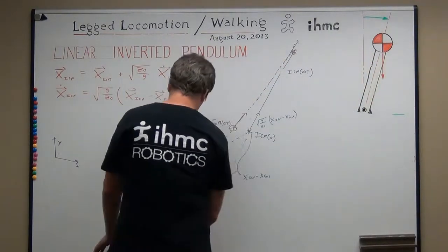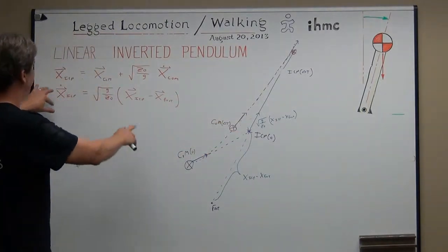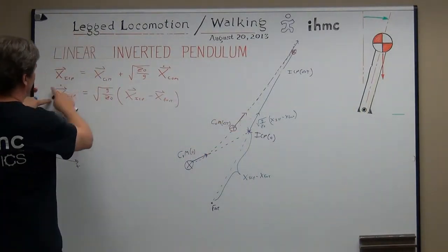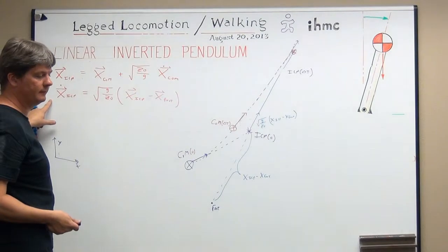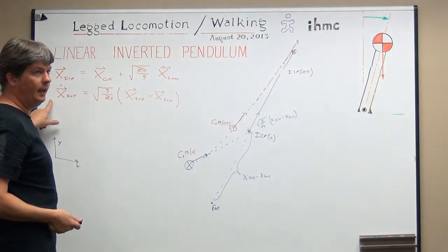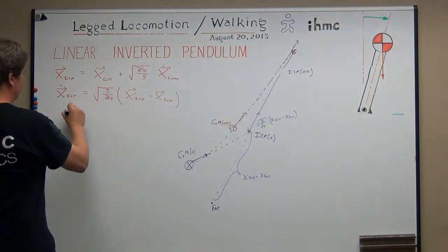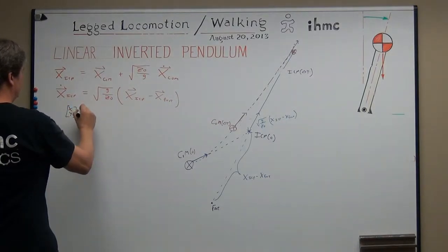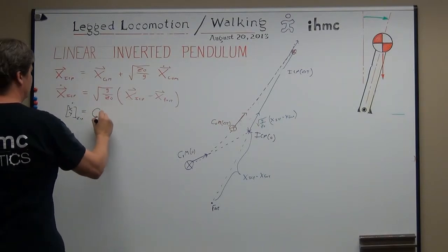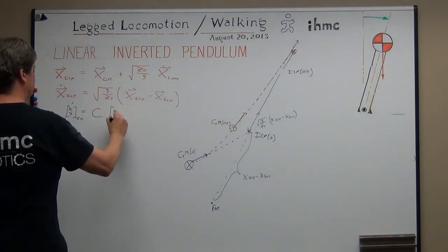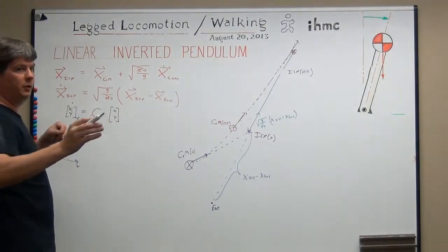So what creates that line in the first place? Is that just an artifact of the fact that we're keeping a constant center of mass height? If we weren't keeping a constant center of mass height, then that would not be linear anymore, correct? Right. It's really because x and y are decoupled. So the ICP derivative is some constant times x and y. Because of that, it's a line: x and y both grow at the same rate.